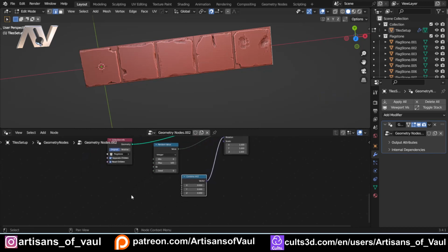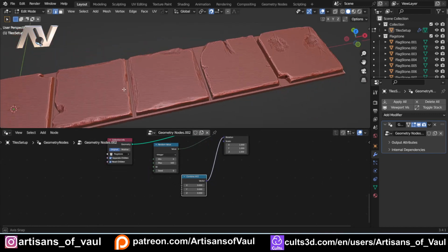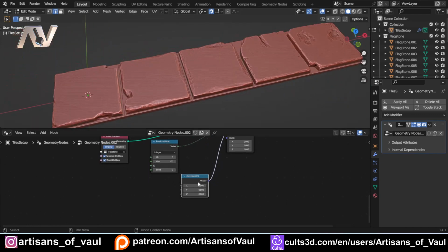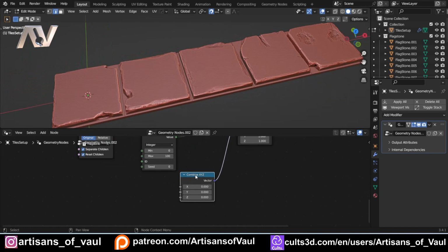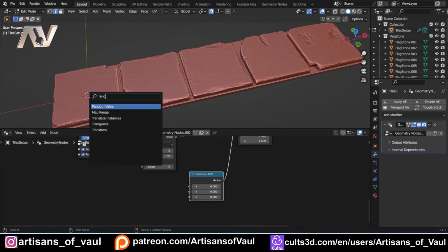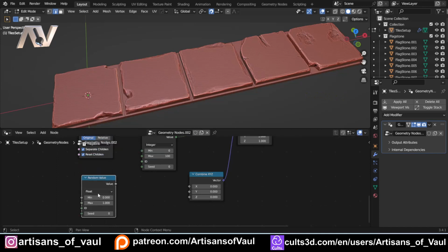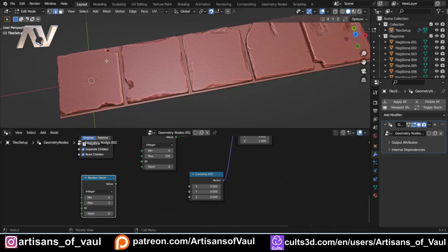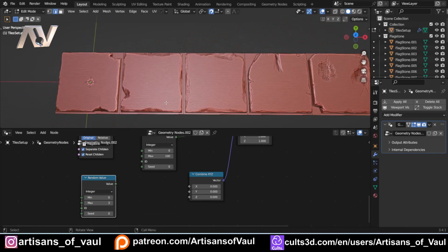And we want to rotate this round, well, multiples of 90 degrees. Blender doesn't seem to like degrees, which agitates me. It seems to work in radians. My brain doesn't particularly like radians, but either way, we'll deal with it. So what I want to do is another random value, and we're going to set that to be an integer anywhere between 0 and 3. So we've got 0 degrees, then we're going to say 90 degrees would be 1, 2 would be 180, and 3 would be 270. So we've got all of our rotations of 90 degrees to make sure that this is going to stay, well, in a sensible orientation.